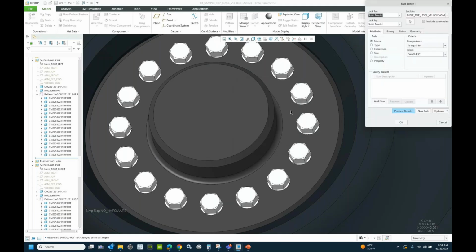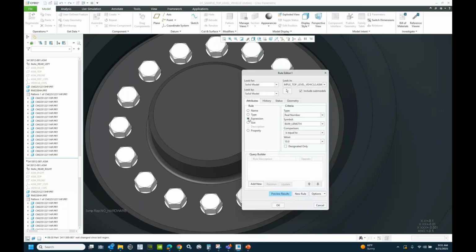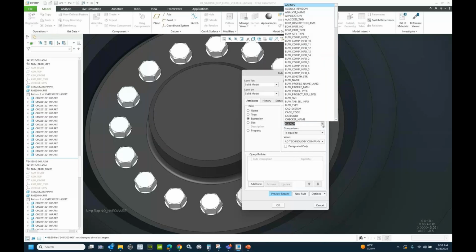And enter. And then here, I'm going to look by expression. When I do this, just like my parameters, I have different types of parameters. I'm going to look for the string parameters. Now, what this will do is give me all of the string parameters that are available in every single part in my assembly. So this list could be fairly extensive, right? And so then I'll use the symbol or the expression, and you can see that it's a pretty good sized list. And again, it's because it's giving me every string parameter from every part within the assembly.